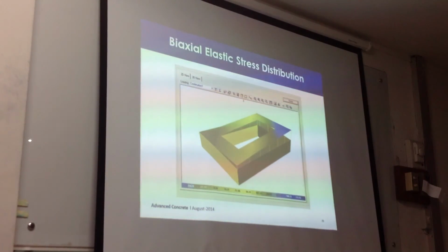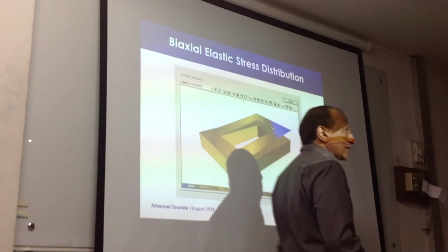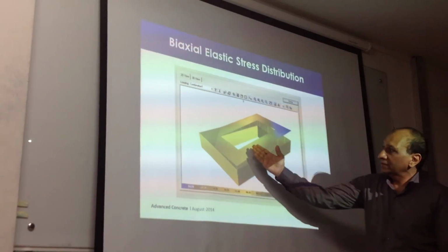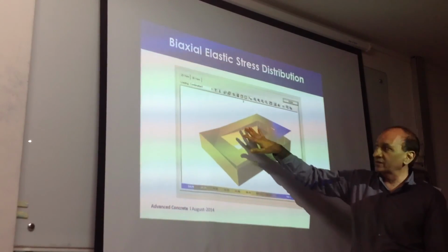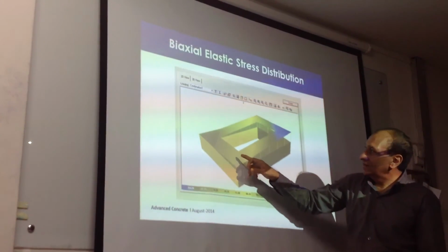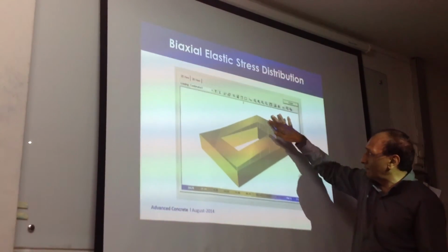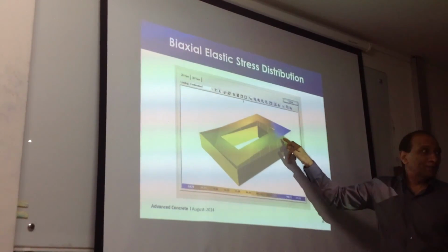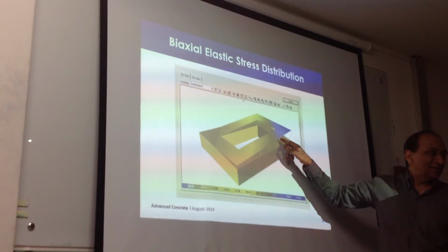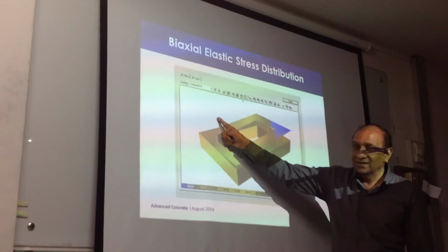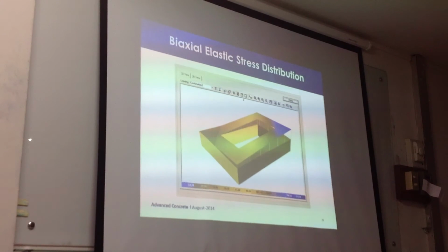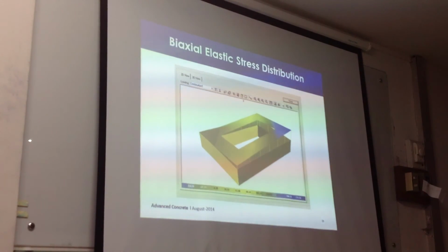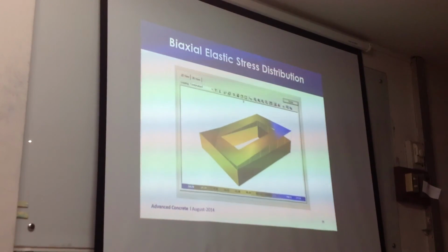This is what it shows you. It is not taken from that program with diagrams. So it shows you that if you put the load here, it will lift up like that, it will go tension here, tension here, compression here, and this becomes your deformed plane, that is your original plane, right? And they are intersecting here. That is your neutral axis, as we call it. So neutral axis is basically the intersection between the undeformed plane and the deformed plane.